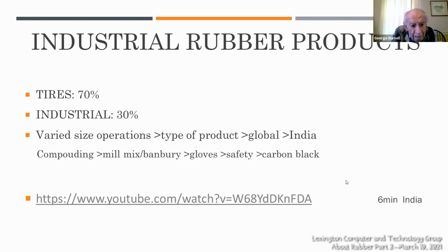And in this one, he's compounding the rubber. He's adding the chemical to it, and then he's mill mixing it. Now, in the rubber industry, you either do it this way, which is the basic way that you mix the chemicals. Otherwise, it's in what we call a Banbury, which is something the size of a room of your house. A Banbury will take anywhere from 500 pounds up to a ton, maybe. But in this, you watch his hands. He's supposed to be wearing gloves. The gloves are supposed to be slit on the back.